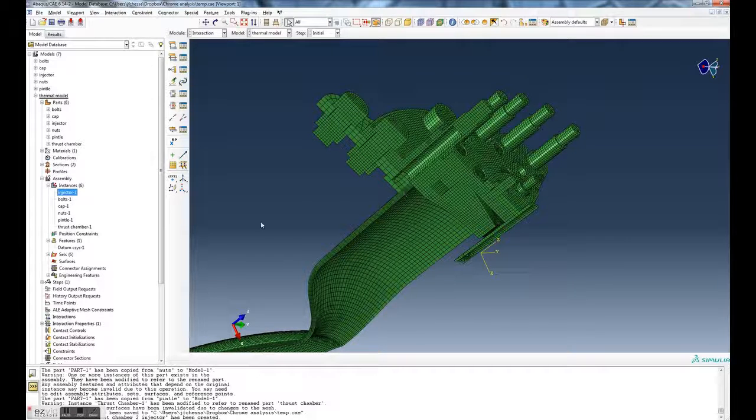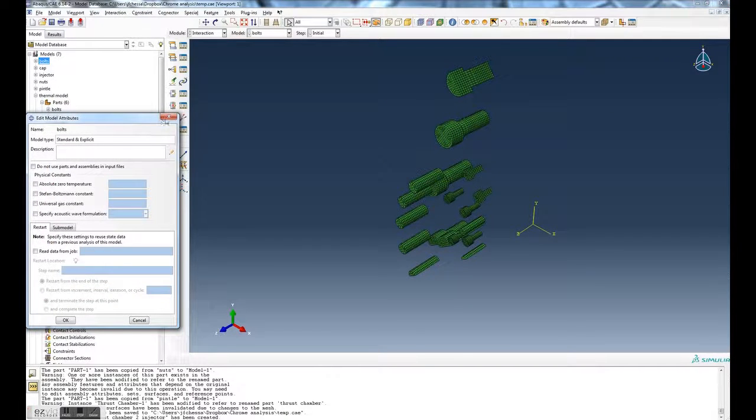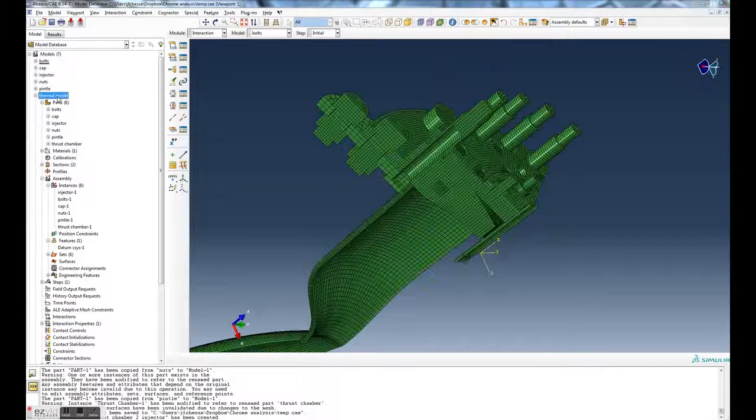But let's go down here and get to where we compute the element strains and stresses. Again, this has to be done on an element by element basis. So we loop over all the elements. It's the same type of loop we did before. But now instead of computing the stiffness matrix, I actually am going to compute the element B matrix, right? So it pretty much goes the same way. We need cosine and sine, and that forms the B matrix. All this stuff, N1, N2, here are the coordinates just like the computation of the stiffness matrix. Length, cosine, sine. So that allows me to get the B matrix.